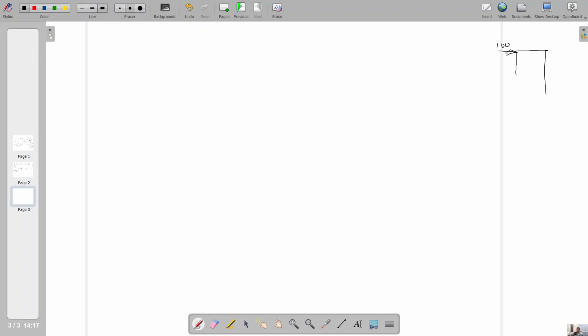For calculating the fixed end moment for non-sway analysis, we need the loading in the middle or throughout the span of the members, but we have only one load and it is acting on the joint. So there is no way of calculating fixed end moment. So there is no need to analyze the non-sway frame. So directly we can go to sway analysis.